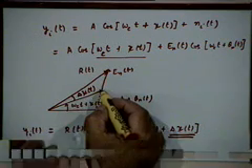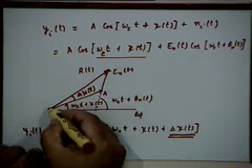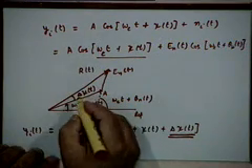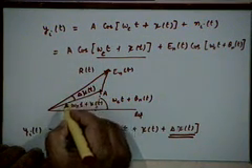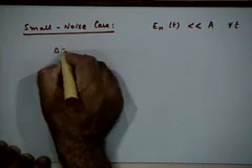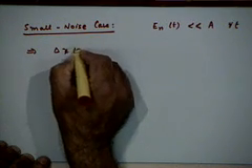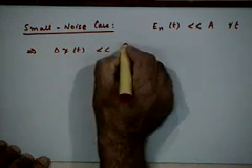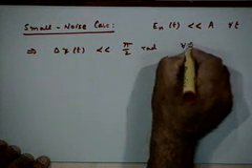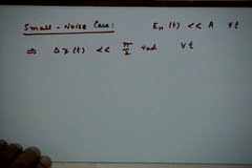Now, in terms of phasor diagrams, what does it mean? We are saying that this amplitude is much larger than this. So basically it implies that this angle delta psi t would be a very small angle. So we can use all kinds of interesting approximations under that situation. This will imply that delta psi of t will be much less than pi by 2 radians for all time.